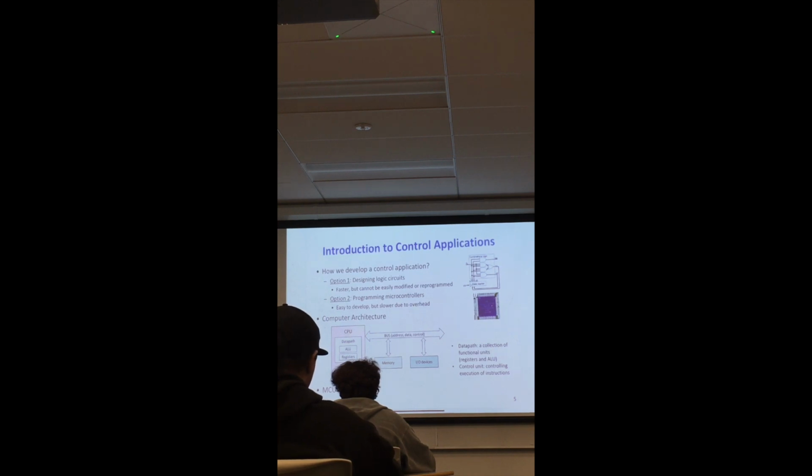Well, disadvantages is, in fact, also speed of processing. Remember, MCU goes through the cycle, like analog to digital conversion or something like this. There are many things related to the speed of processing. There's nothing that can beat discrete implementation, because it is so tuned to the applications, so tailored to the application that the speed is incredible.